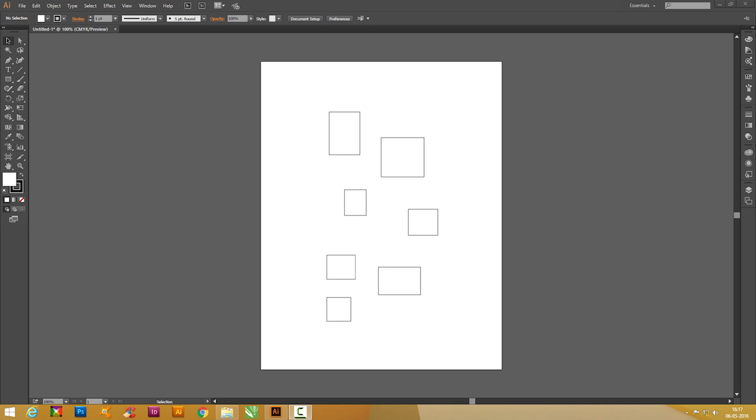I'll select the selection tool. I'll come here and I'll click on the object that I want to select, and that object gets selected. Okay. So similarly, whichever object I want to select, I have to take my mouse over the object and I have to click on it. So that object gets selected. Okay. And now I can do multiple selection by holding shift and clicking on the objects. Okay. And now I can do the same multiple selection by clicking and dragging like this. So on whichever area my selection area crosses, those objects will get selected.